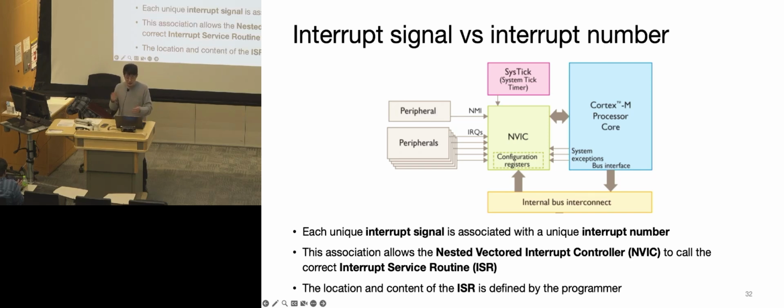The programmer decides what to do when a certain event happens, in our case mainly from the peripherals. Something's been triggered, and then you tell the system or other peripherals what to do inside of that ISR, the handler function.